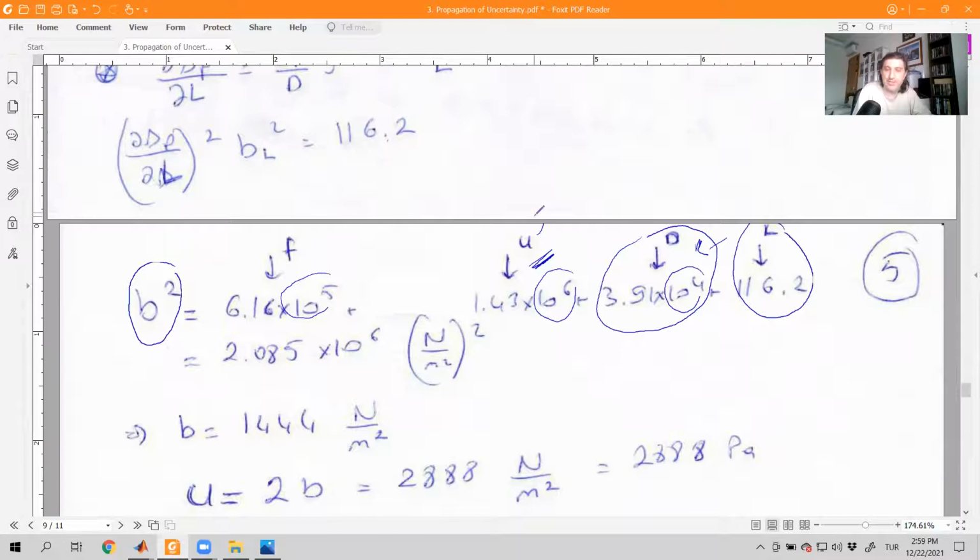the uncertainty of velocity, what does it depend on? It particularly depends on diameter and time. So diameter and time readings are pretty much important to determine a correct velocity. Fanning friction factor has an effect in terms of uncertainty close to velocity, slightly lower than that. But if you recall, fanning friction factor also depends on velocity and diameter. So again, we have diameter here, and we have diameter also which affects the velocity.